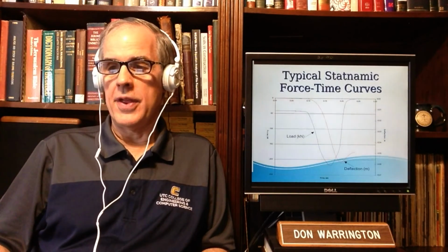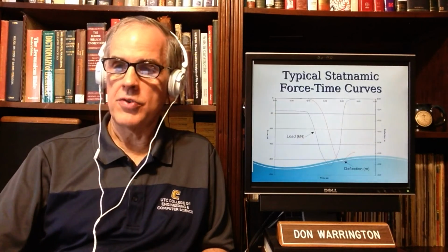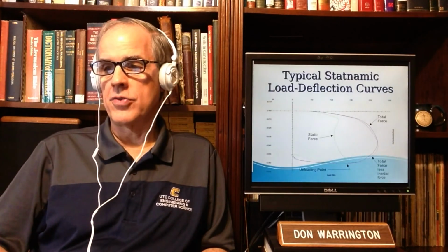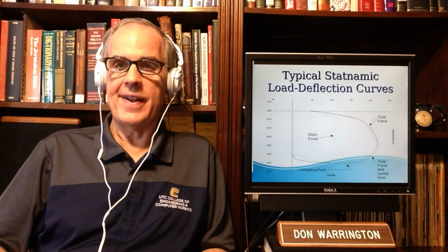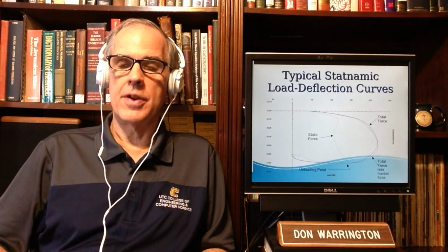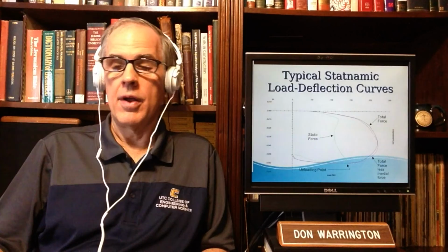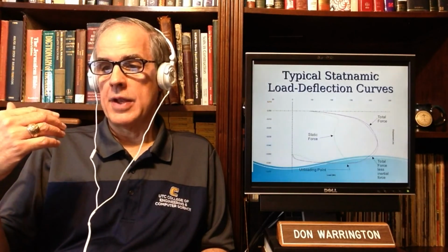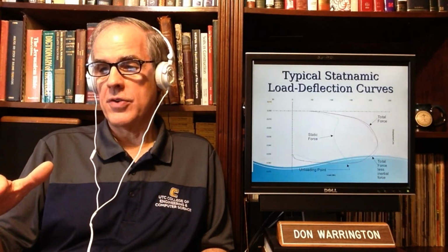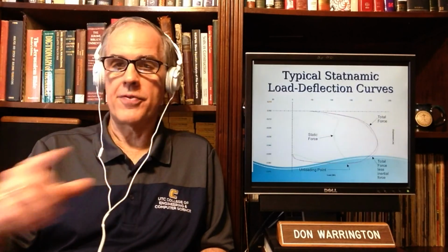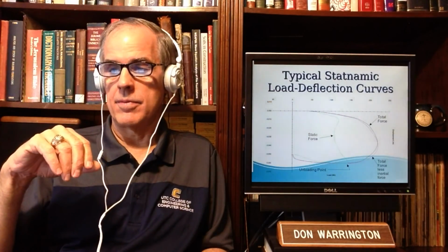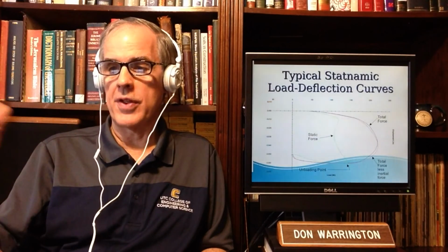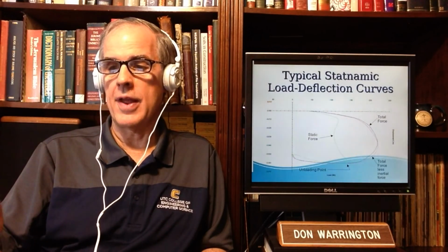Once you get those, you take them and process them into a simulated static load test. You do that with dynamic testing as well. You get the total force, the inertial force, and then a static force out of that.